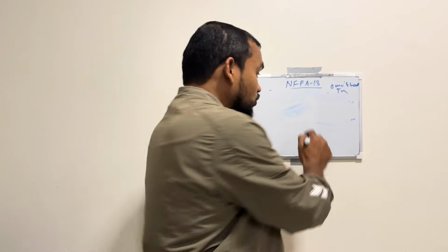Only the following electrical equipment is installed, like dry type, or liquid type with class K fluid. The room is fully enclosed with 2 hour fire rating. If the electrical room has a 2 hour fire rating enclosure, we can omit the sprinkler. No storage of any kind is permitted in this type of room. We can omit the sprinkler in the electrical room.